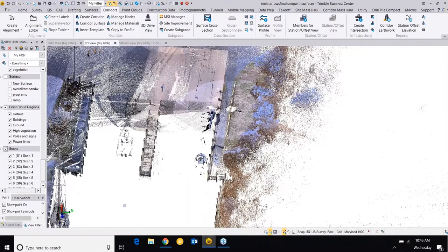So check that NGS monument, shoot it, and note that everything from there forward is from this monument. Then I checked into the tidal datum because it's very hairy. If you're going through an 8-foot tidal change and you're off 2 feet, that's a hell of a lot of water you have to take out, and somebody's got to pay for it. Did that answer those two questions? I'm trying to make sure I fielded them right.